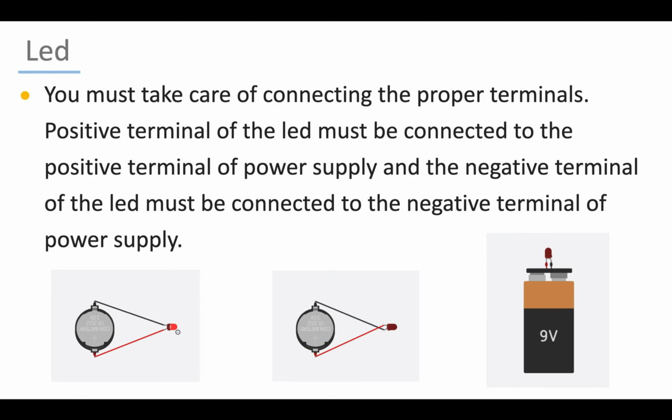Now after this, let's move to the connections. So you must take care of connecting the proper terminals. Positive terminal of the LED must be connected to the positive terminal of the power supply, and the negative terminal of the LED must be connected to the negative terminal of the power supply.